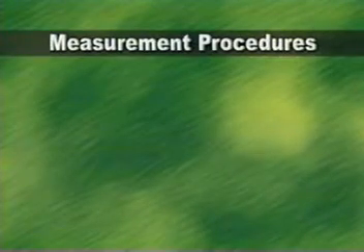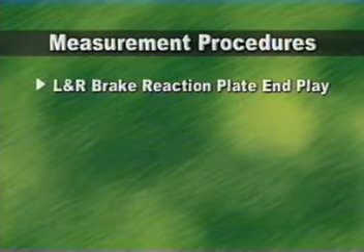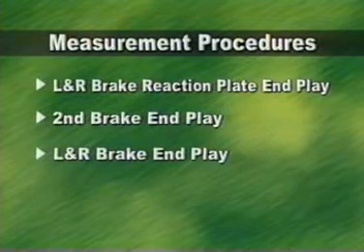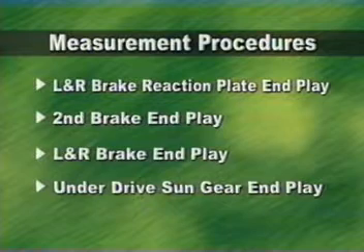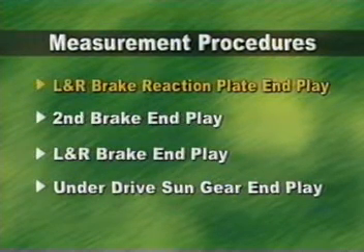Be careful about measurement procedures when measuring the end play of second brake and low and reverse brake. First, the end play of low and reverse brake reaction plate. Second, end play of second brake. Third, end play of low and reverse brake. Fourth, end play of underdrive sun gear. First, let us explain the measurement and adjustment of end play of low and reverse brake reaction plate.